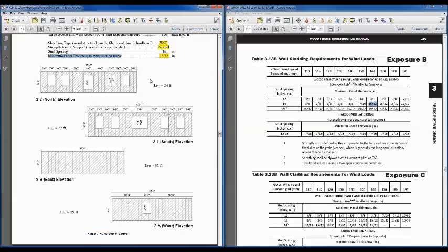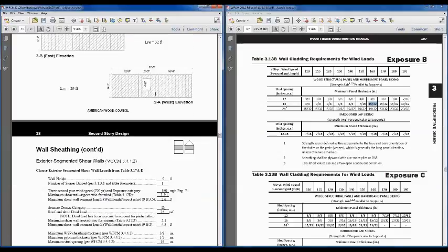These are the wall details. They come from the front end of our book. We're probably just going to look at the north elevation wall for this next example. I'm going to point out that it's got 24 feet of full height sheathing, and that's in between these window and door openings. So we've got 3 feet here at each end, 3 feet between each of the windows, and then 6 feet between the windows and this master bathroom window here in the center. So keep that in mind as we jump to page 38 of our example problem.